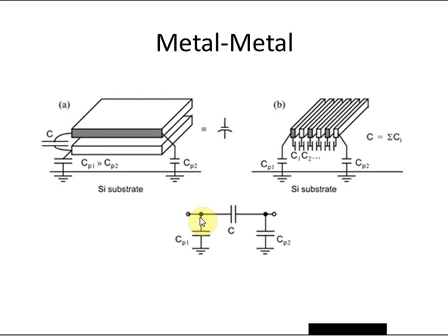Another way to make capacitors out of the metal interconnect layers above the substrate is shown here on the right. This is an interesting technique that's become very popular now in scaled, very small feature size CMOS technologies because the interconnect can be made with such fine pitch that actually the wires themselves, if minimum width wires are looked down upon from the top, they actually look like this. They're sort of these bars on edge. They're a lot thinner than they are tall. So it makes sense at that point, and also they can be packed very close together. This is of course important for digital routing applications.